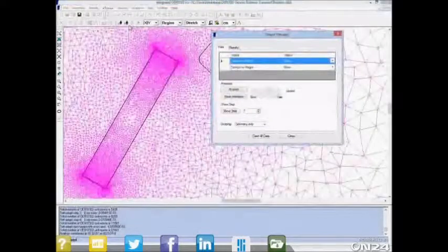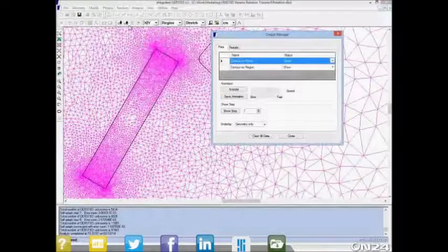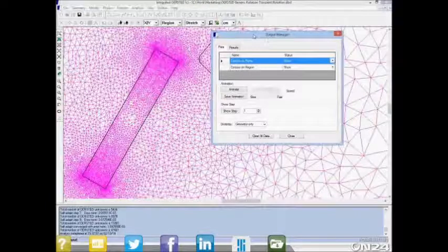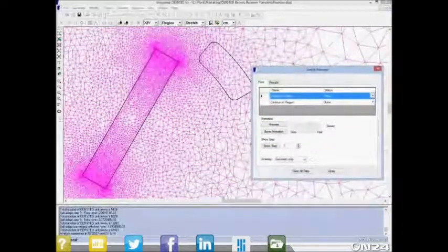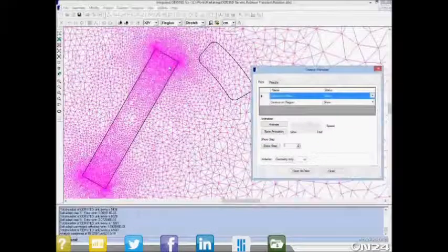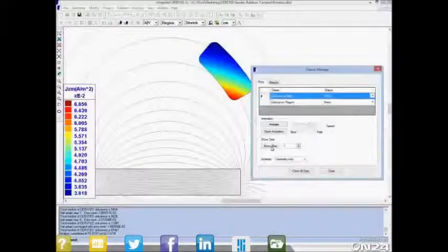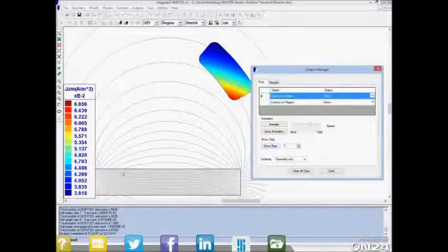So now that the parametric has run, we can see that the magnet has rotated by some amount in total, and 2 contour plots are available. Now the outputs were set up to take occasional screen captures of these contour plots. So if we look at step 1, what we can see is the flux lines as the magnet is in the 0-degree position.